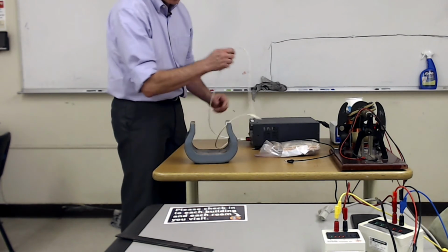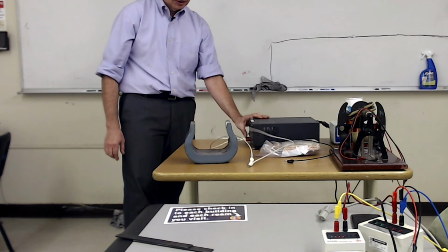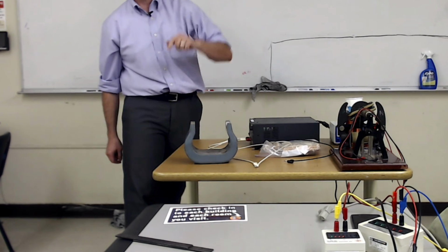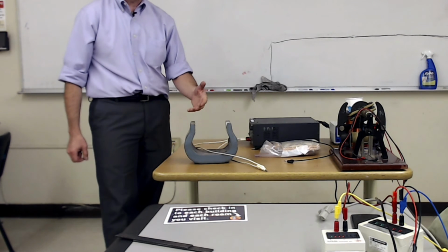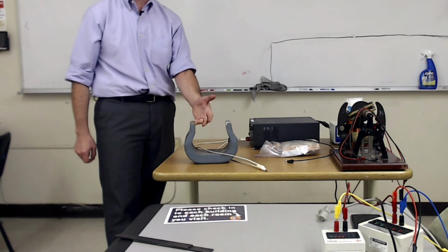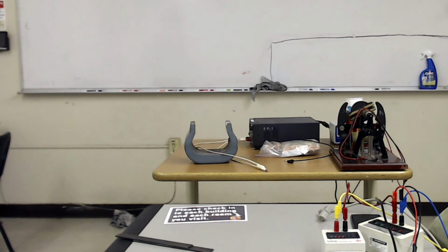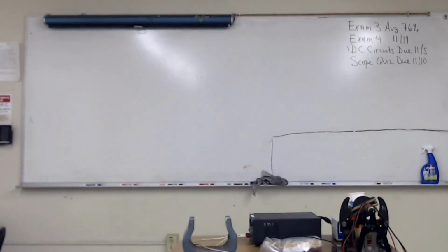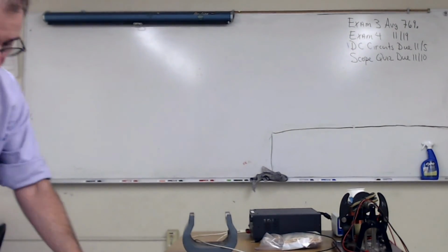Did you see the wire jump out? Yeah. Do it one more time. Of course, if I had the current going in the opposite direction, the wire would want to move down. So you can see a magnetic field can exert a significant force on a current carrying wire. And so what we're going to do is derive the equation. We can determine this experimentally, but I can derive it from our knowledge of the force on a charge in a magnetic field. So let me do that.